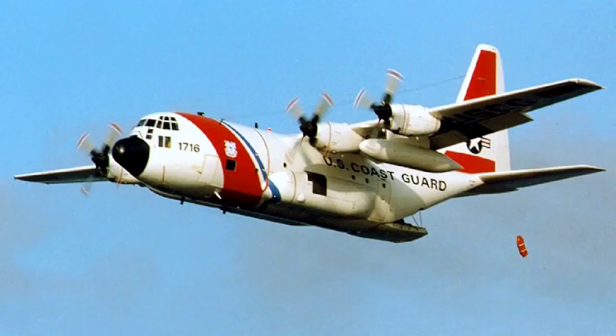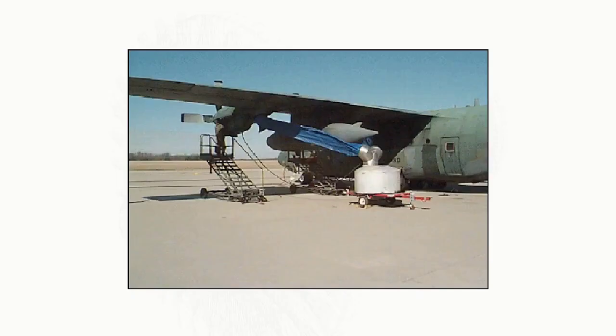If the major cause of contamination is salt ingestion, as might be the case with an aircraft which flies for long periods low over the sea, like this US Coast Guard C-130, then a timely rinsing of the compressor with fresh water can avoid use of harsher treatment which otherwise would be required. A compressor rinse can be carried out either while motoring the engine over on the starter or while running the engine at idle speed. This procedure is known as a desalination wash.